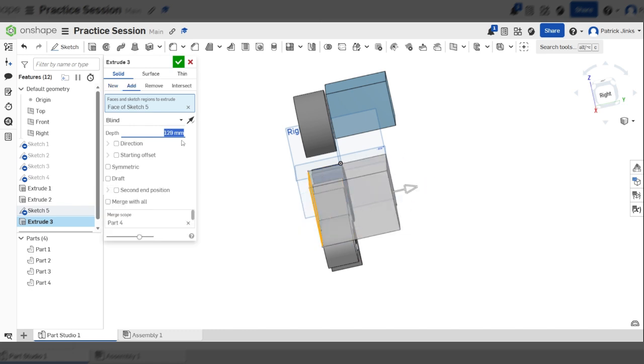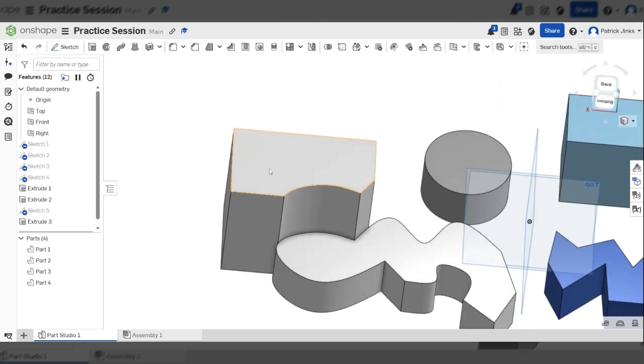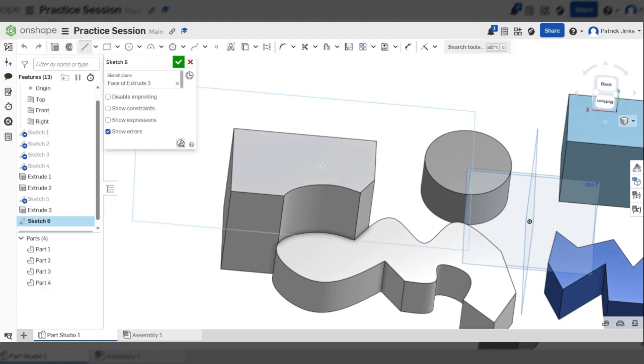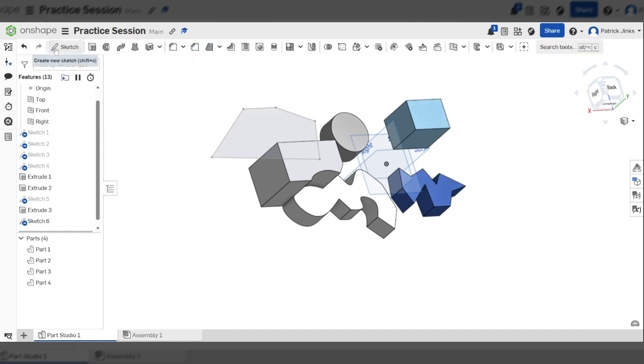And I can start building up the shapes I've made as long as it's a flat surface. I'm just going to make another sketch on that surface, and as you can see, it's flat on that surface. I can overhang it, but it's still sitting on that surface. I don't even need to click the tick if it's a closed shape. I'm just going to click Extrude.